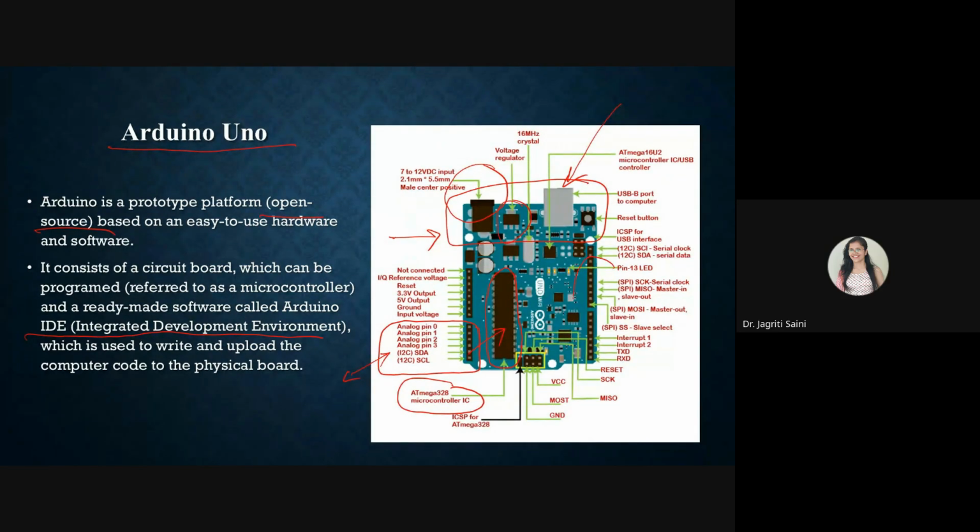This side we have digital port. All these pins, they come under digital port. However, the pins here have multidisciplinary function. Some of them can act as SPI interface that we recently discussed about. The starting 2 pins are used for the transmit and receive with UART communication ability. Then on the top of this, you will also have I2C communication facility, SCL and SDA lines. So all these are integrated on the digital port.